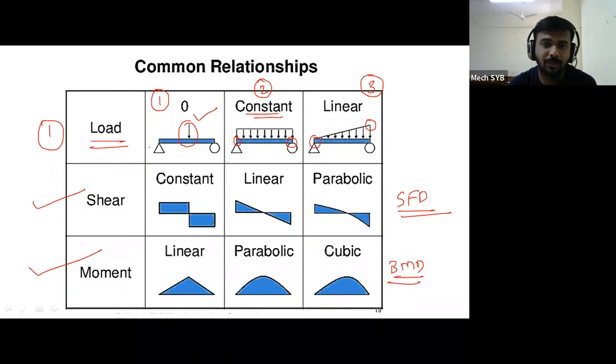Then, using the shear force calculation, if we want to draw the shear force diagram and the type of load is a point load, you have to represent that particular calculation by using vertical lines or horizontal lines. See, in the second row, if you look at this point load, in the case of a point load the shear force diagram is indicated by vertical and horizontal lines.